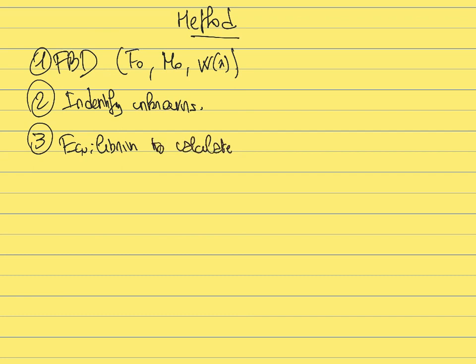That is always important, but in this case it's going to be even more important, because you will need those unknowns. You will need to know the value of the external forces that are applied at the two edges of the beam to find the integration constant. So step 4 in this case: now you will need to find all the values that you need to find the integration constants.